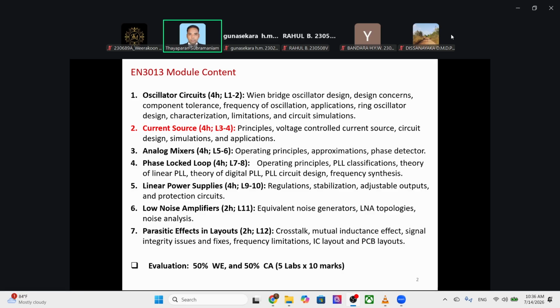In reality, identify few parameters which can change. For example, temperature, power supply variation, right? What are the other parameters? It will change. List it out. Try to change 1 or 2 parameters and see the effect. That's what you should do. Okay, try to change, for example, supply voltage variation. You can easily mimic that condition in the lab, right? When you change the supply voltage gradually, you should be able to measure the variation. Therefore, you had to come up with certain arrangement. I think you know how to do that now by this time, right?